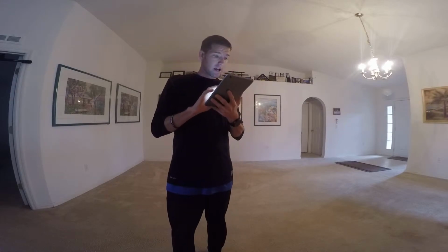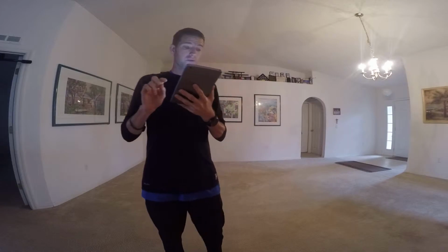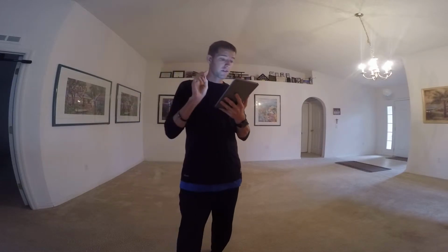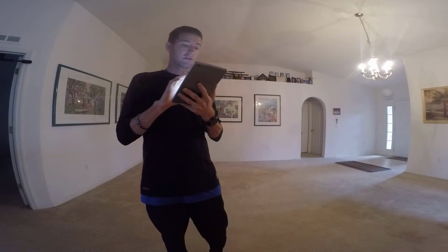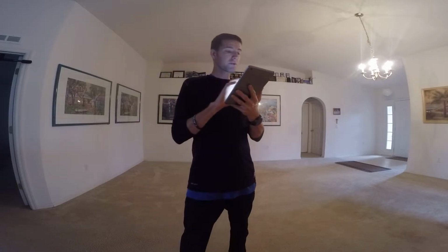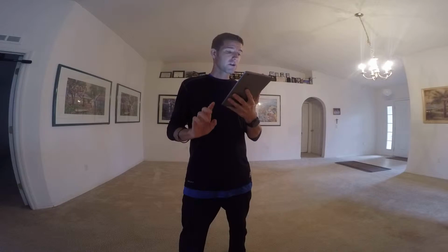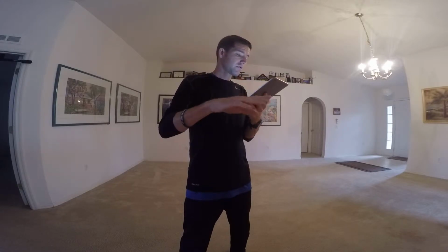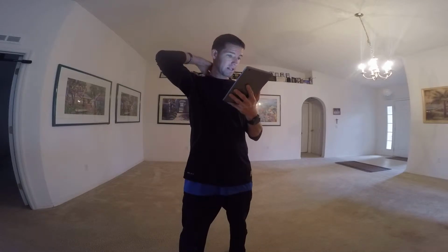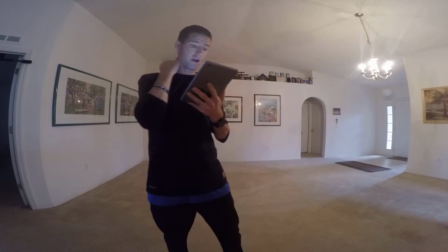Forward flight. In steady forward flight with no change in airspeed or vertical speed, the four forces of lift, thrust, drag, and weight must be in balance. Once the tip path plane is tilted forward, the total lift thrust force is also tilted forward. The resultant lift thrust force can be resolved in two components: lift acting vertically upward and thrust acting horizontally in the direction of flight. In addition to lift and thrust, there is weight, the downward acting force, and drag, the force opposing motion of an airfoil through the air.